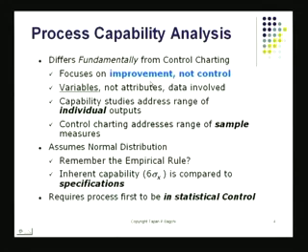Any process that you bring about will always have some variation. What we have to do is make sure that variation does not take the output beyond the specification limits. Such a process will generally be under the influence of factors which cause too much variation. One of the tasks in process capability analysis is, first of all, to obtain a measure of how good the present as-is capability is. If it turns out that parts of the process are producing output going beyond the specification limits, we have to tighten the process.